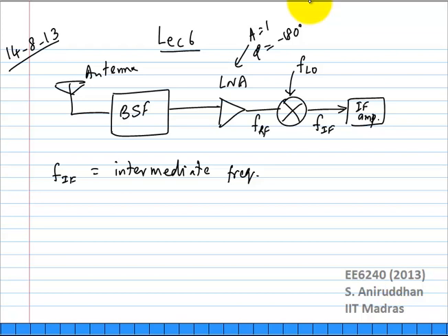Okay, at least okay. So, we'll come to that. But primarily in terms of parasitics, what kind of parasitics are you thinking of? What kind of parasitics lead to this feedback problem? Some input to output capacitance. Okay, what does the input output capacitance depend on for a normal amplifier? The sizes of the devices.